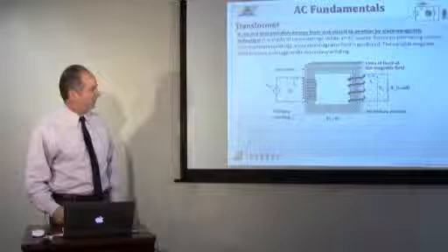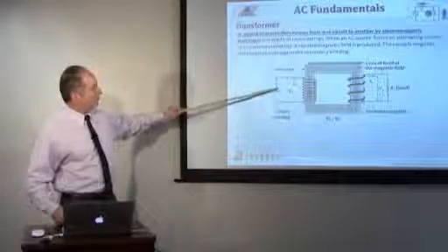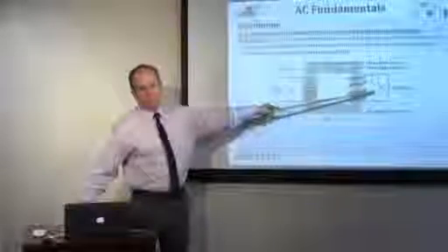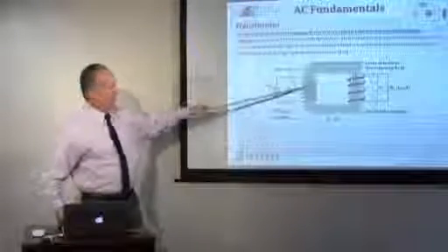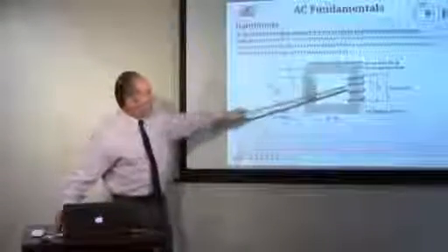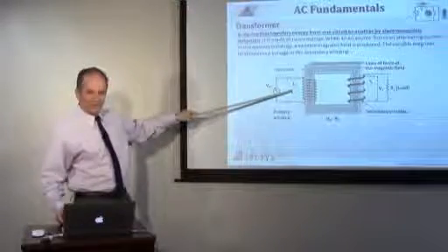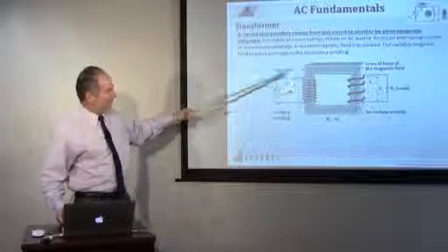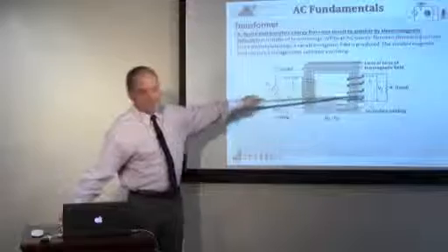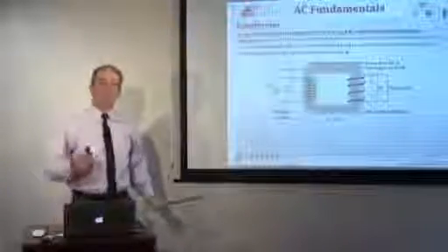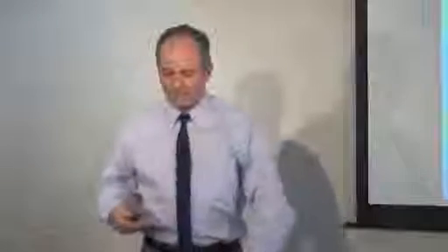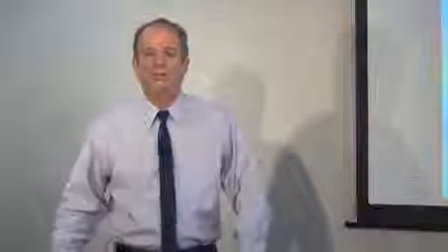It uses Faraday's law. If you reverse this, if we put a voltage on a low voltage side, we will produce a high voltage side. And when you increase the voltage, you reduce the current for the same amount of power. If you go in this direction, if you decrease the voltage, you'll increase the current because it's got to be the same amount of power. So that's the characteristics of a transformer. A transformer transforms the voltage of the source into the required value for the load by simply selecting the appropriate turns ratio.